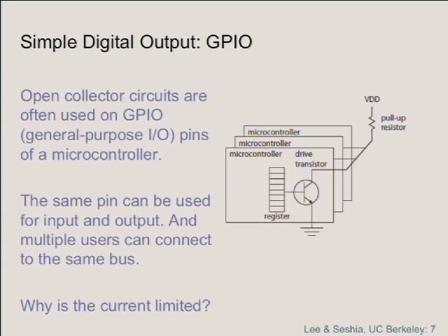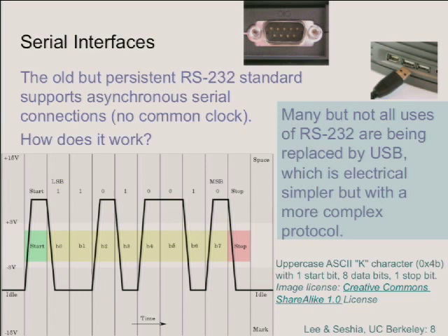Serial interfaces work a little bit differently. The RS-232 standard is the one that was established to talk to teletypes. Okay, and it persists. It's a really awkward standard, primarily because it's electrically awkward. The voltages are plus and minus 12 volts, which is, digital logic doesn't do 12 volts anymore.